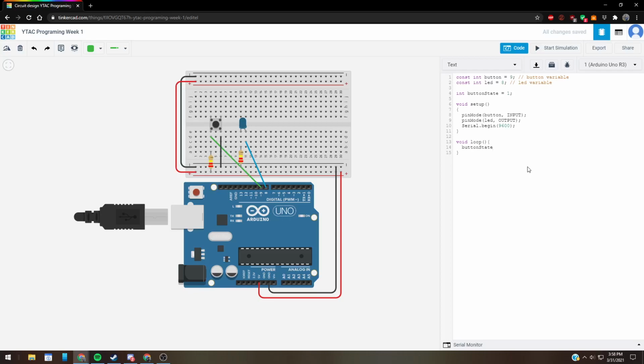So we're going to do that by setting this variable equal to the digitalRead function of button, our variable up here. Close it with a semicolon. Basically what digitalRead does is it determines if it is HIGH, which is on, or LOW, which is off. Other programming languages will say true is 1, false is 0. This is essentially saying on is HIGH, LOW is off.